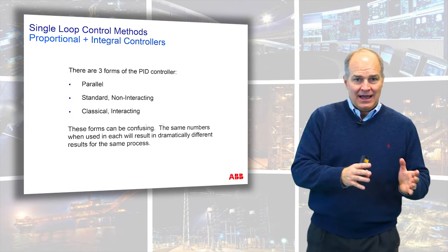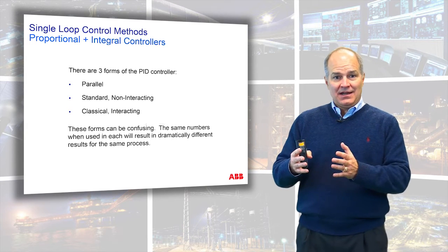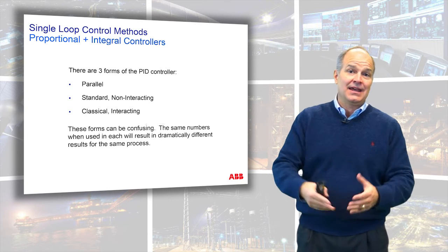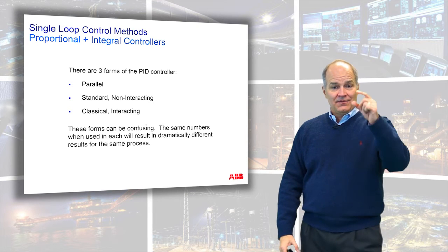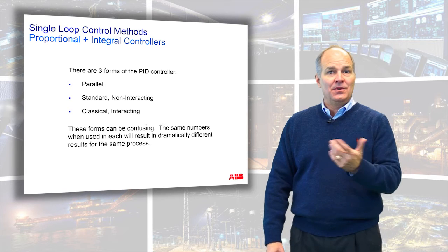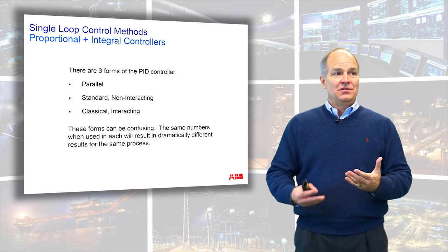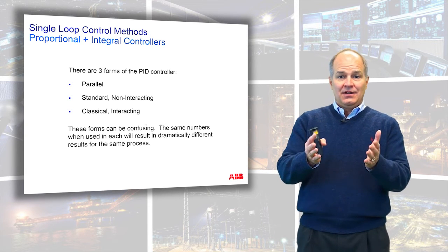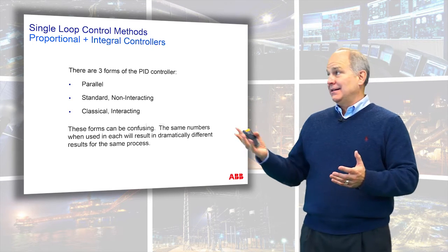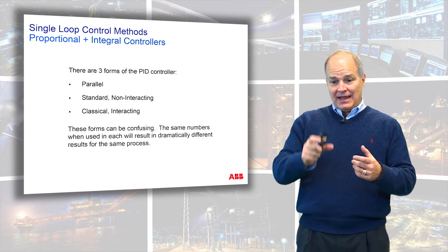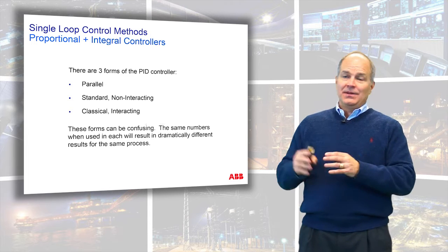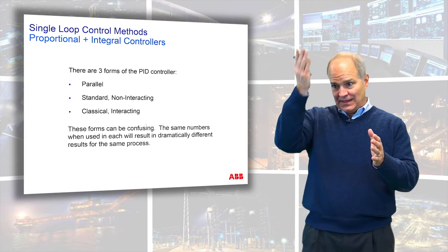The algorithm changed. And when the algorithm changes or the mode changes or you go from one vendor to another and they've changed, and even today, one controller could be set up, now it's an option. You say, which form do you want? Which makes it real fun. Used to, you could tell by looking at a vendor what kind of control form you had. Today, you actually have to go in and look at the attributes of the controller to see which mode that it's in.